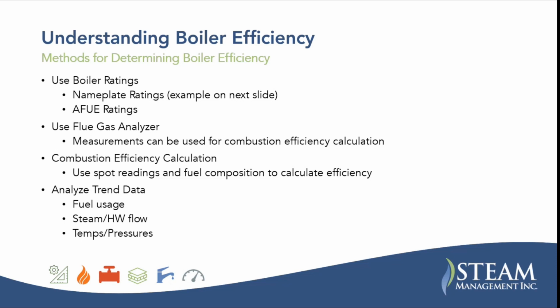But I'm generally going to stick to these types of things. So one would be to use the boiler rating. So then you're looking at the nameplate ratings, which we'll give an example of on the next slide, just to determine efficiency in general terms. If you have published AFUE ratings for the boilers, that's great to compare.